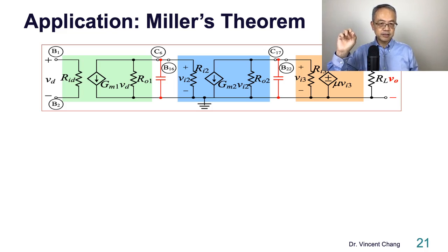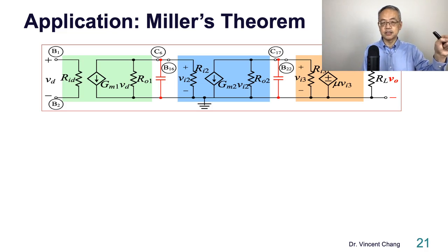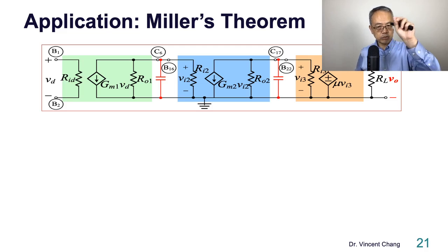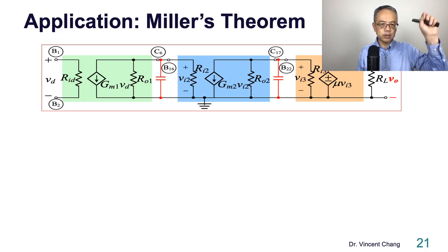The capacitance is proportional to admittance and inversely proportional to impedance, so it should be multiplied. For the one on the left, I didn't put this on the slide, so you can maybe pause and write down: the one on the left should be CC multiplied by 1 minus K. The one on the right, the output capacitance, should be CC multiplied by 1 minus 1 over K.